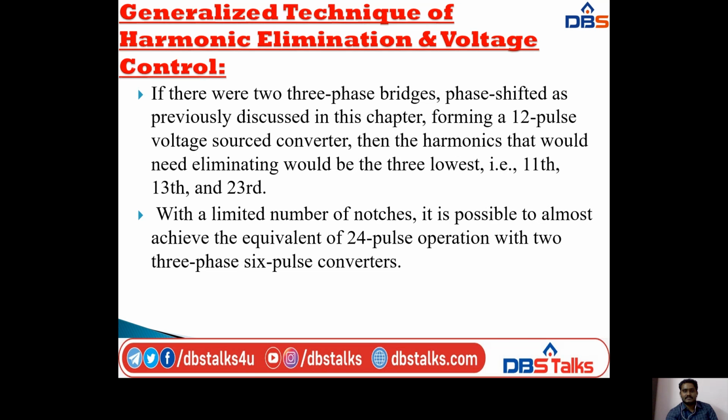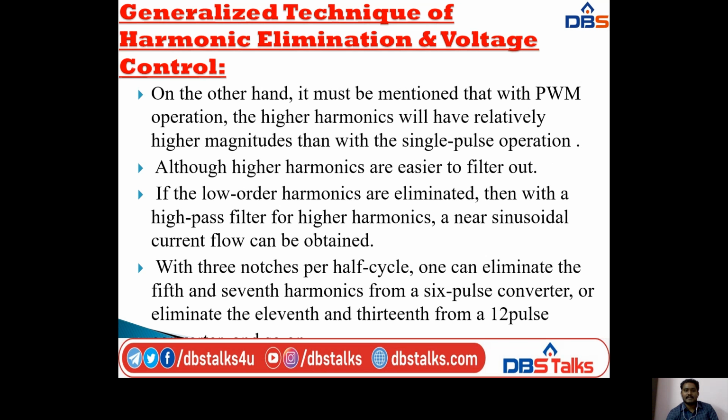With limited number of notches. And next, on the other hand, it must be mentioned that with PWM operation, nothing but pulse width modulation operation, the higher harmonics will have relatively higher magnitudes than with the single pulse operation. So previously I discussed about 3-level converter and transformer connections for 12 pulse and 24 pulse and 48 pulse also.